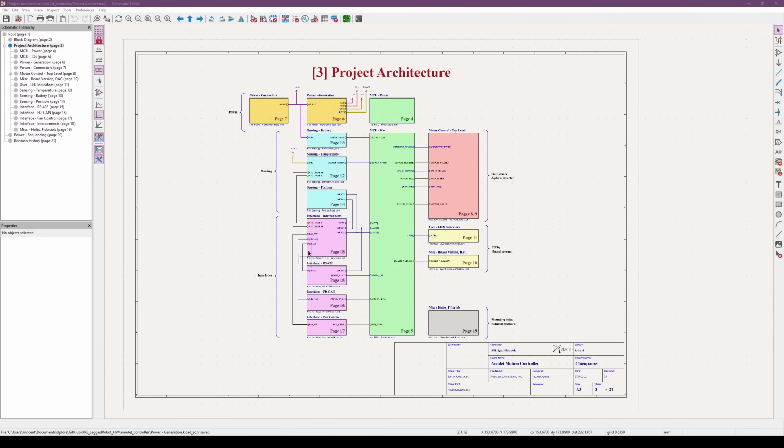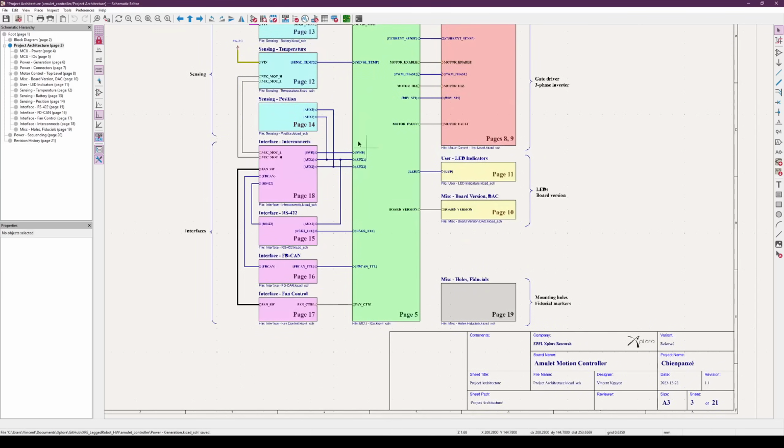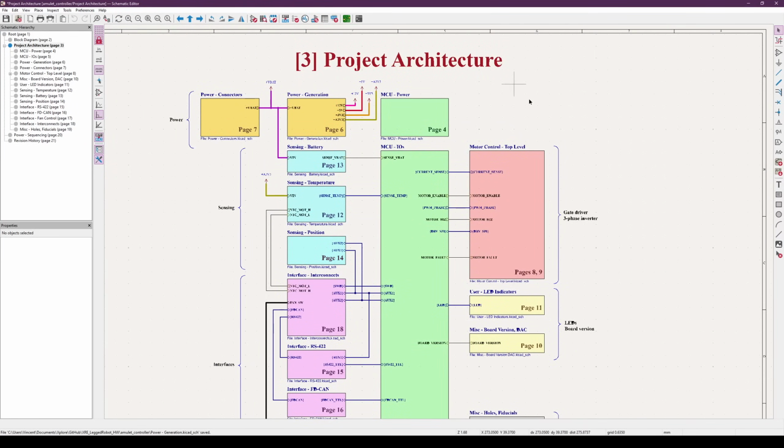There are quite many ways to structure your KiCad project, such as flat schematics or hierarchical schematics, or just having everything on the same page. And the choice of which structure suits the project will really depend on a case-by-case basis. What I really like doing for more complex projects is a hierarchical schematic.